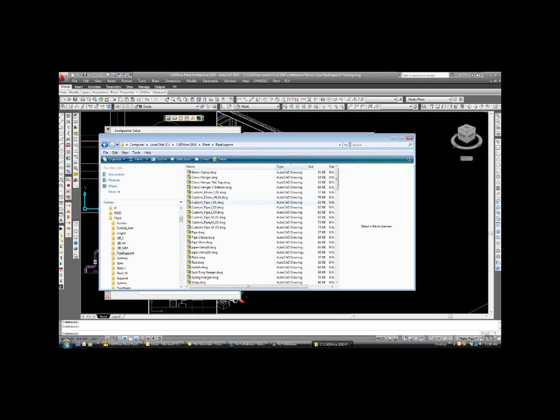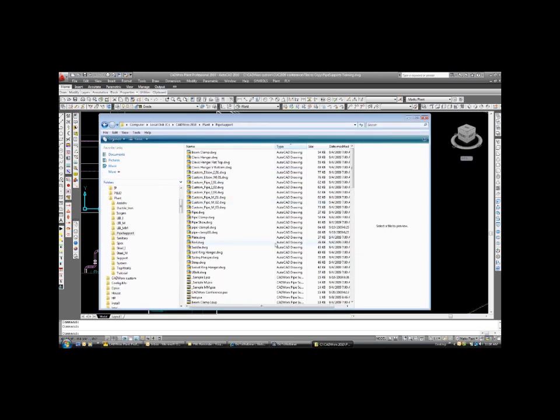When you go to change or customize a file, these are the files you'll be changing. Everything that is used inside the pipe support modeler palette needs to be put inside this one pipe support directory. Myself, I keep this pipe support directory out on my network so all my designers have access to the one set of files that we've customized, and they'll all use that one spot. You just have to redirect that in your Imperial CFG file.